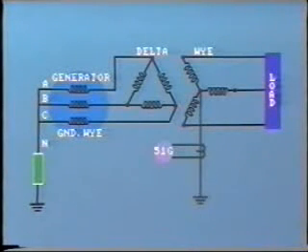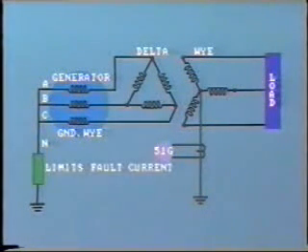We have pointed out that in utility practice, the equipment is usually solidly grounded at voltages above 40 kV. Now, at lower voltages, sometimes equipment is grounded through an impedance to limit fault current. An example is the generator neutral. The impedance may be in the form of a resistance or reactor, or perhaps a grounding transformer. The main objective of this is to limit the available fault current.